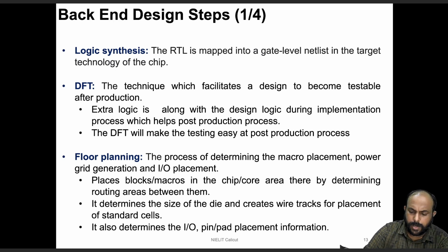So what happens in this step is, you have a particular design, and alongside that design, certain extra logic is inserted, so that post production testing of the design logic will become easier. It gives a certain amount of controllability and observability to your design. So the purpose of DFT is to insert additional logic into the design so as to make the testing of the chip easier post production.